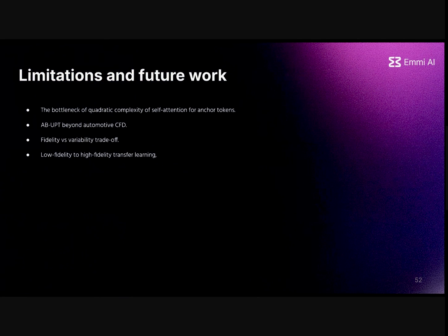So although this is all great, we are not there yet. So there are some limitations and future work. On the data sets we tested, mainly AMD-ML and DrivAer ML, we were able to have very good consistent performance with a very small number of anchor tokens, like 16,000 or 32,000 was enough. But for more complex geometries and more complex phenomena, it's very likely that you need more anchor points to properly model the physics. And at some moment, the quadratic complexity of the self-attention between the anchor tokens can still become a bottleneck. So we have to address that at some moment if the simulations become too complex.